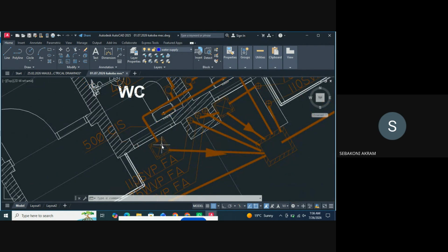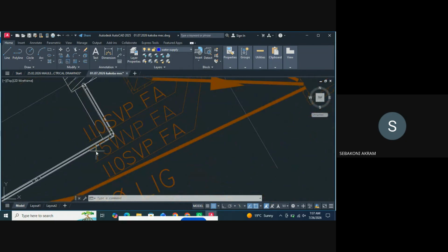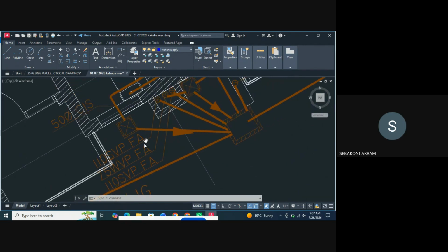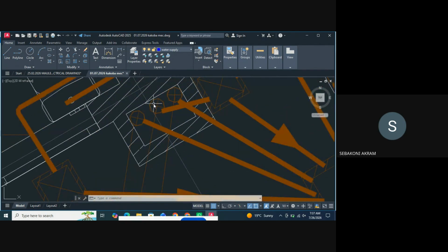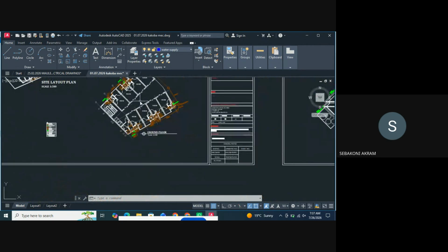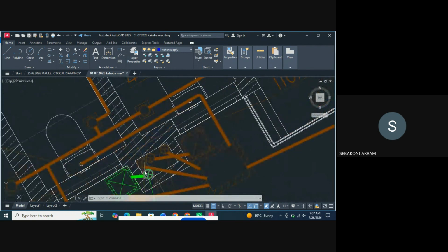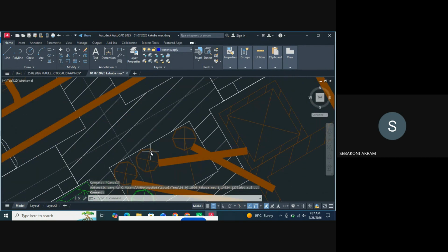Then we come to the drain. Then here you can see we used 75. Why? For the wastewater. Remember, wastewater is the one connected to the sinks. There are multiple sinks at this floor. If you go up to the next floors, remember there are already 4 floors for this project up to top. So you're expecting about eight of the sinks being connected. Though the 75 will be enough, you don't expect all those things to be functioning at the same time. You getting me? So 75 will be fine.